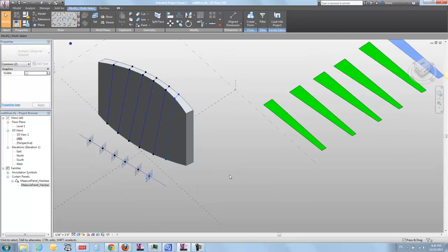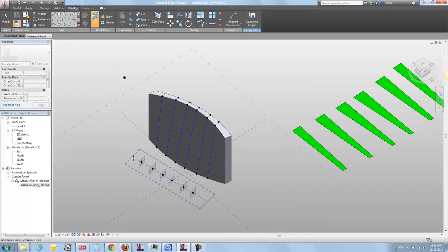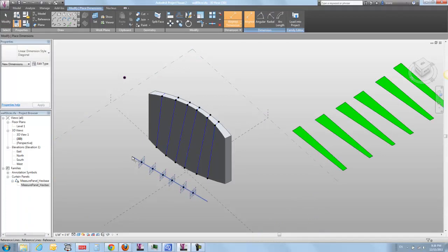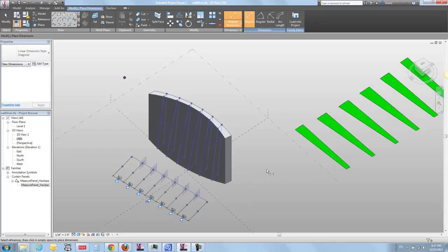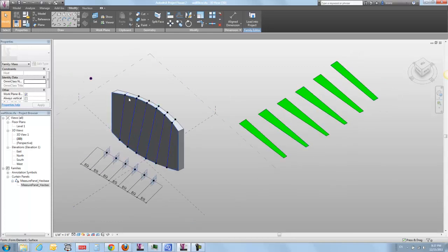And then I can just go and, using some other standard tools, identify the work plane here. I'm going to do a little equality constraint so that all of my points are equidistant from each other, like so. And now it's just going to think about that for a second while it straightens itself out. And so you can see now I've got each one of these guys nicely spaced from each other and arranged as a projection basically from this point along those guys.